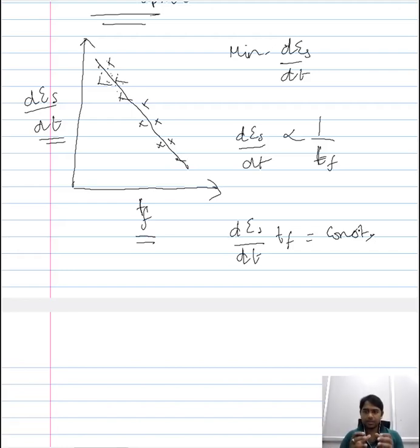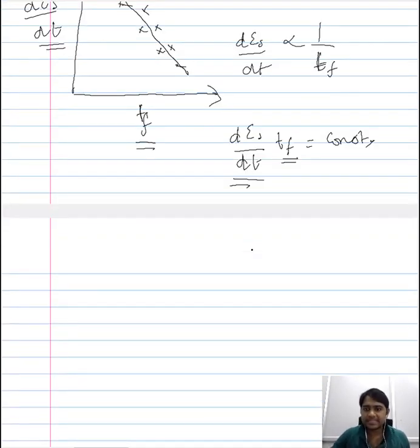So from the numerous stress rupture tests that we perform, we end up having a relation that states the product of the minimal creep rate and the time taken for the failure in a given test is a constant. Now this relation helps us to predict the failure of the material when you have a definite creep rate. Supposing you perform one stress rupture test or a sequence of stress rupture tests, and then you are able to identify the constant for a given material.